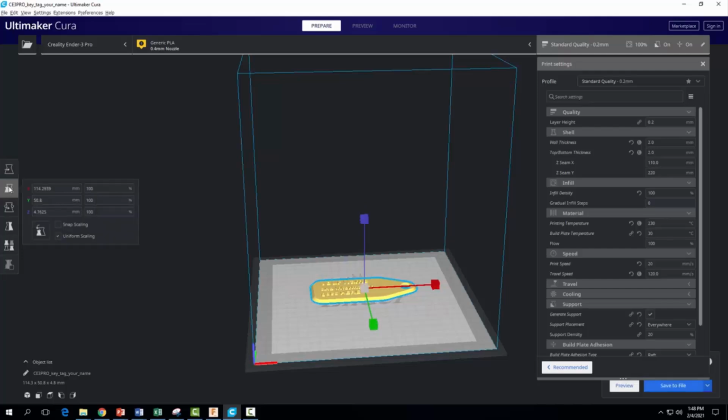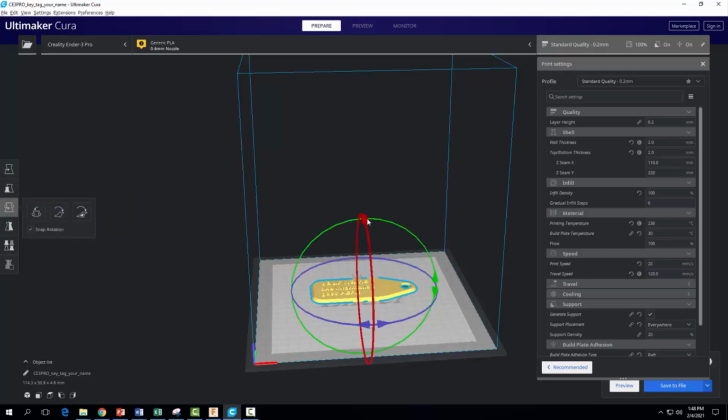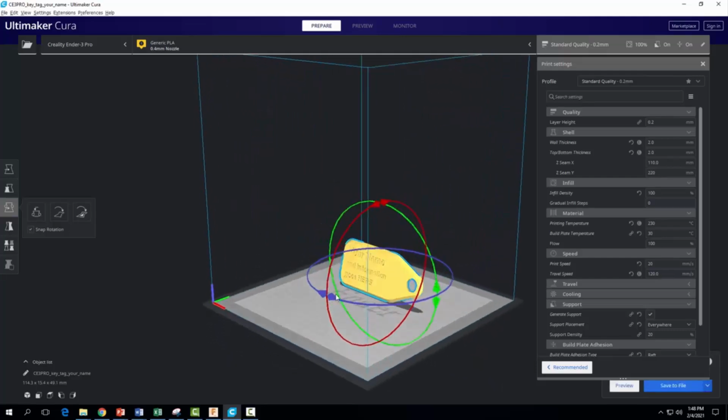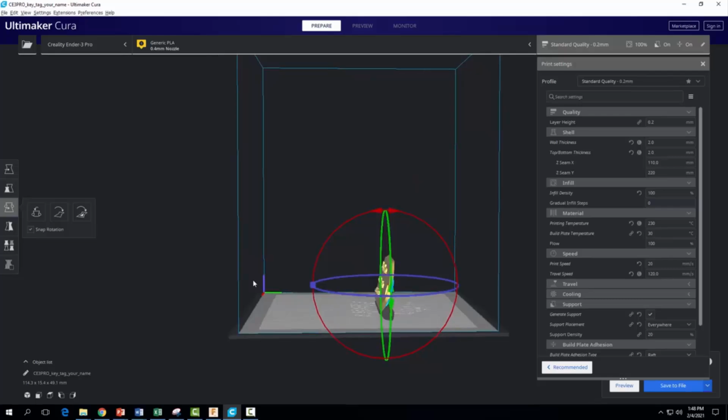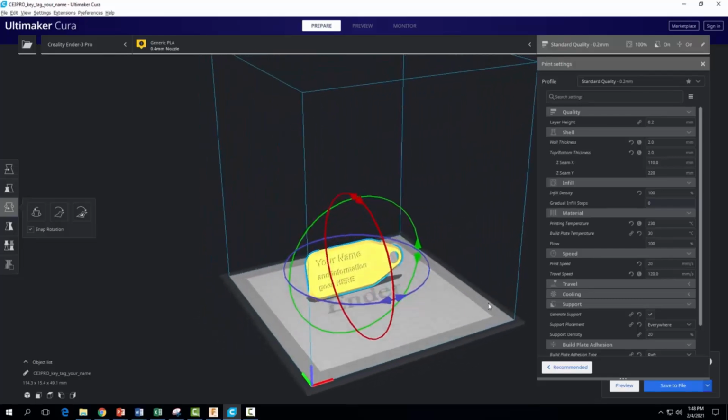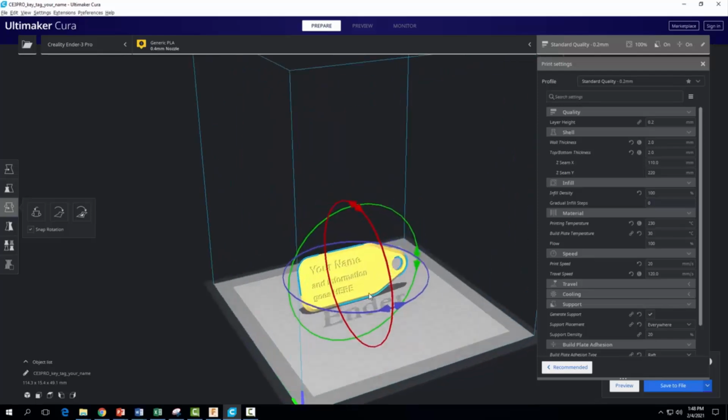You can make the object smaller or larger, okay? And you can adjust the scaling if you don't want it to be uniform. And over here, you can rotate the object, okay? So by turning the object back and forth, okay? And if you right click on your mouse and hold the right mouse button down, you can move around and see the object from various positions, and you can zoom in and zoom out with your mouse wheel.